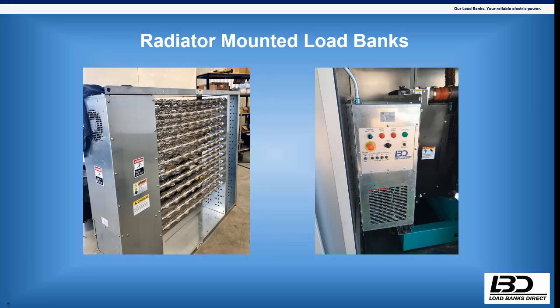Then we don't want to be restricting additional airflow through that radiator either, and cause potential issues with the generator cooling properly. So that custom size is very important. And then I have a great example on this next slide showing you what not to do when these are sized wrong.